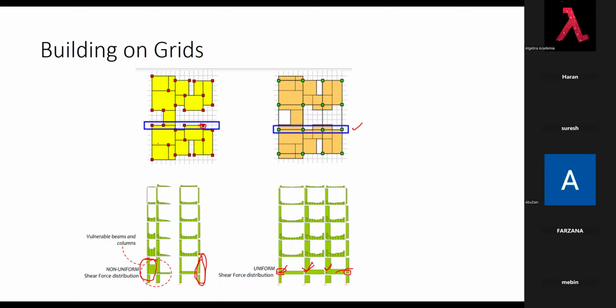So here, the same uniform column size will not work out. You need to make this column bigger, only considering the shear force. Because of the shear force alone, you get a much higher demand for V. You need to increase the column size, and this will make our structure have stiffness irregularity. So this kind of building will have more stiffness irregularity.